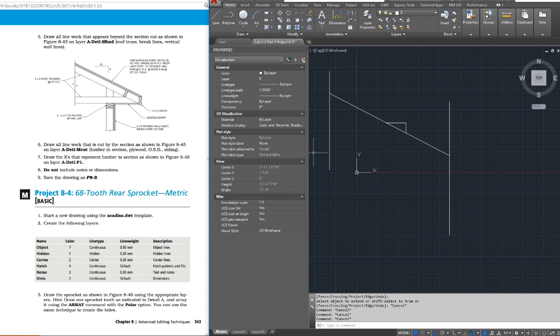Now you're going to have to read what it is that we're putting on this roof, and I'd like you to try to draw it to scale. So it tells you that we're using shingles, number 235 shingles over 15-pound felt. I think that's what that says. It's kind of small right there. Half-inch standard grade, that's the slope. Plywood roof, nailed to the truss. And I'm looking for the size, so right here. There's the size of the plywood.